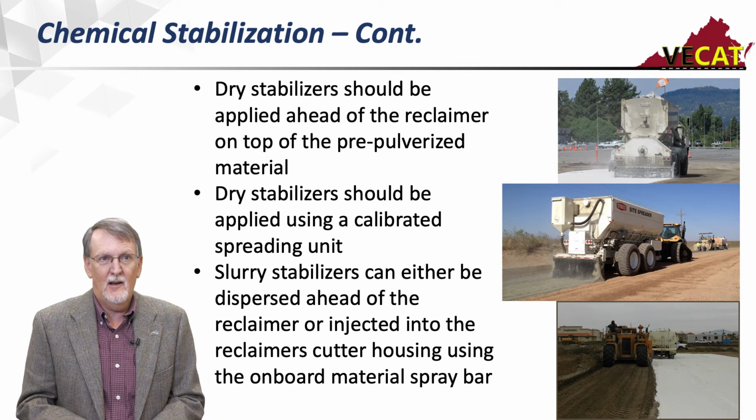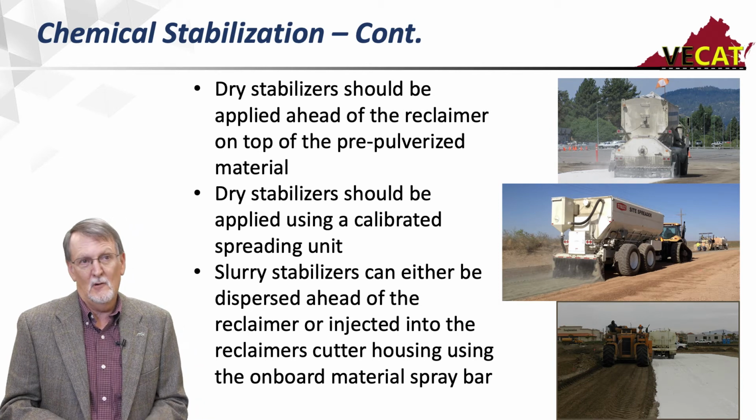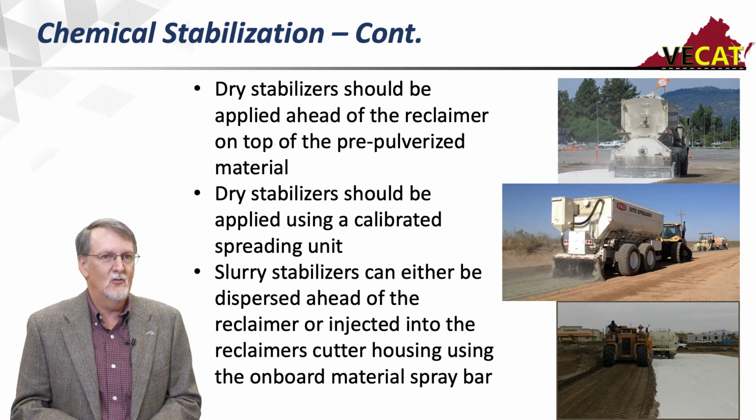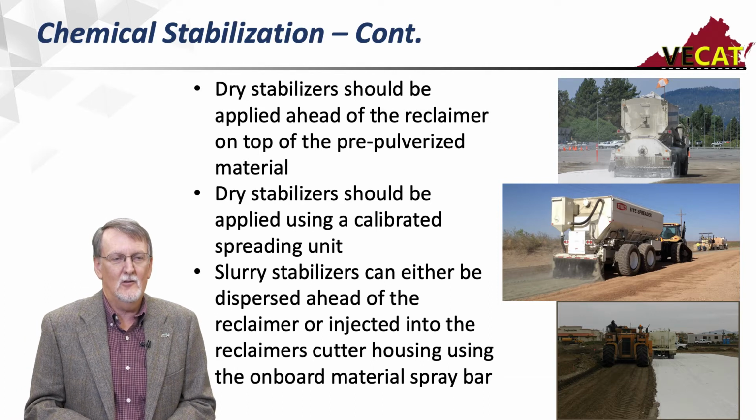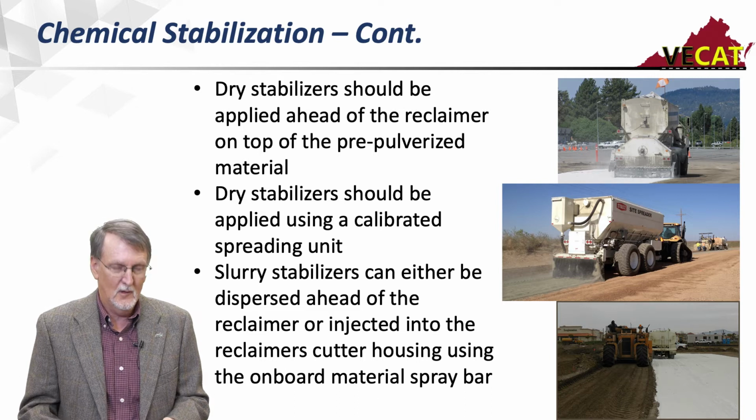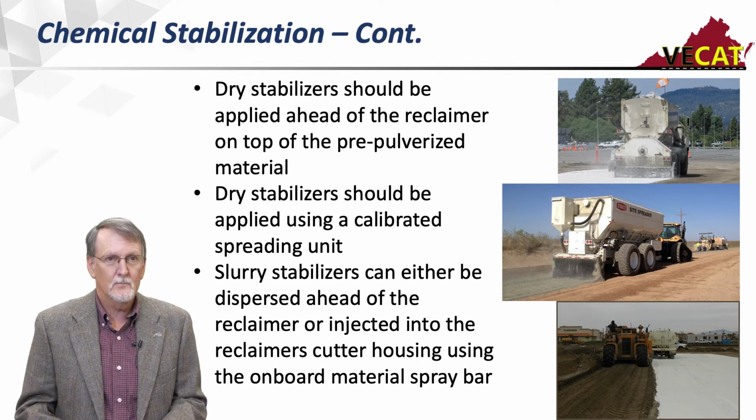And slurry stabilizers can be dispersed ahead of the reclaimer on that second pass, or better yet, we're going to inject it into the reclaimer's cutting housing using the onboard material spray bar, and that will get you much better mixing. So it can be done either way.